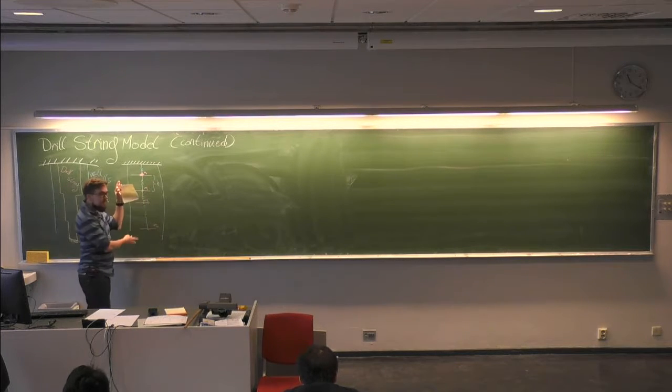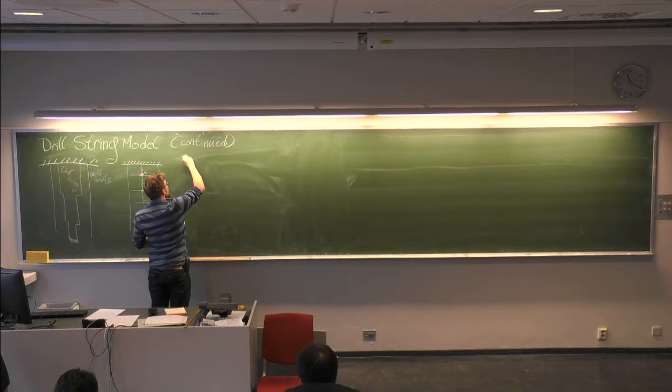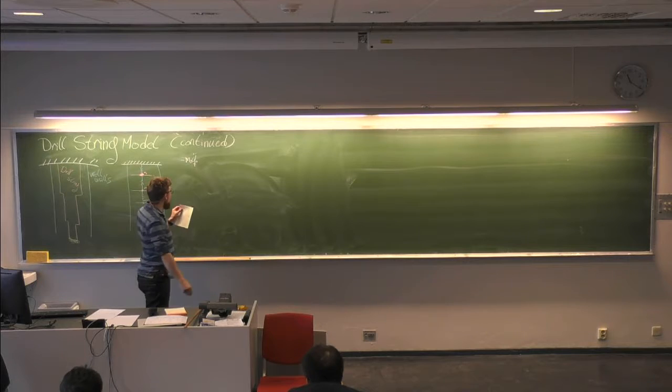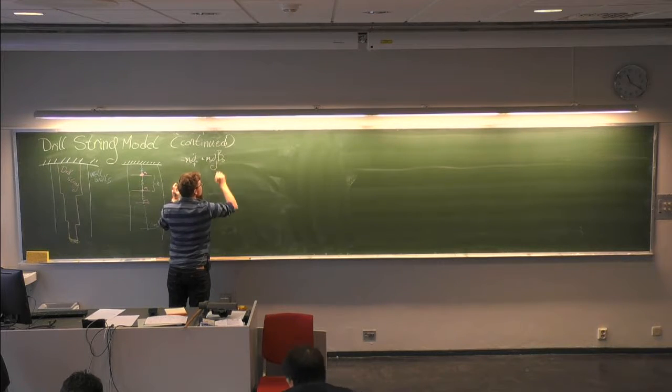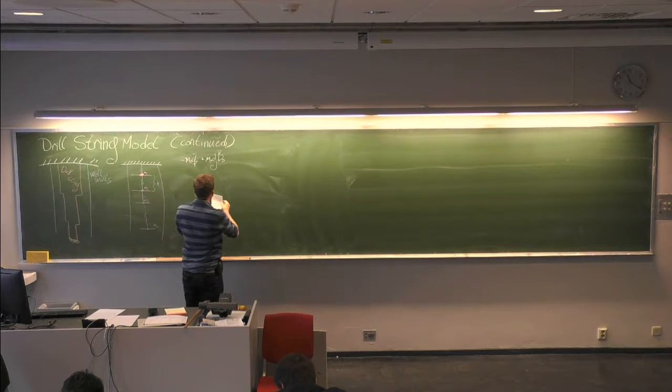To solve this system, we get a system of equations, which looks like m0, the mass, q, the displacement. We need it twice derived in time to get acceleration. Then we had gravitational force with some kind of buoyancy factor. So if it's buoyant, then less than just m times g.